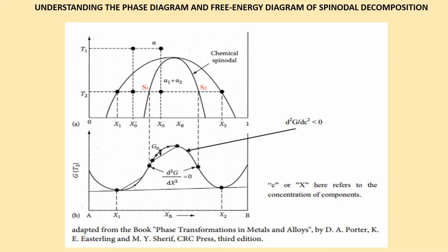There is no thermodynamic barrier to the growth of a new phase, that is, phase transformation is solely diffusion controlled here. To reach the spinodal region of the phase diagram, a transition must take the material through the binodal region or the critical point. Often phase separation will occur via nucleation during this transition, and spinodal decomposition will not be observed. To observe spinodal decomposition, a very fast transition, also called a quench, is required to move from the stable to the spinodally unstable region of the phase diagram.